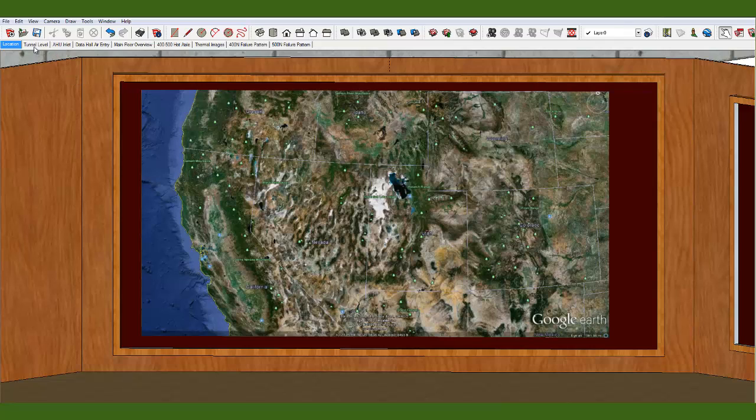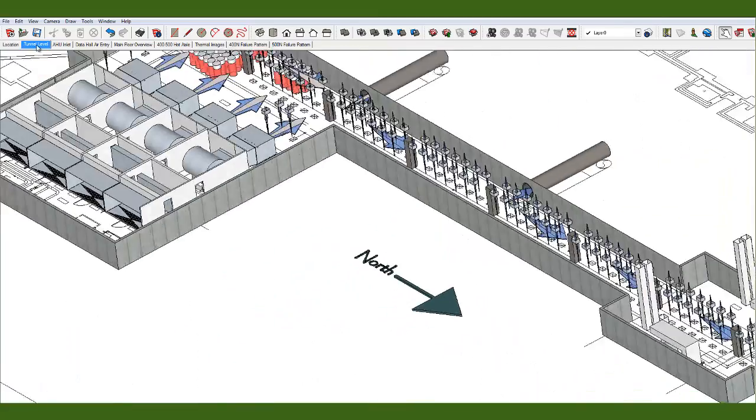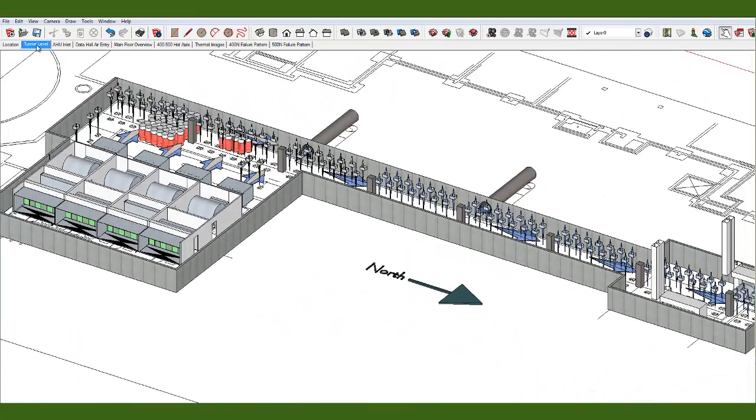So what we did here was to first lay out the air tunnel system underneath the data center, and that's what we're looking at here. And when we inspected it, we found that there was contamination down the south end, and it lessened the further north you went up the data hall, the air tunnel rather.